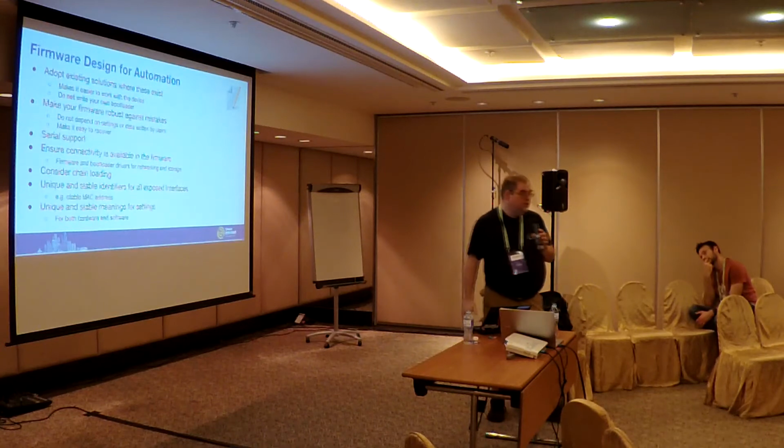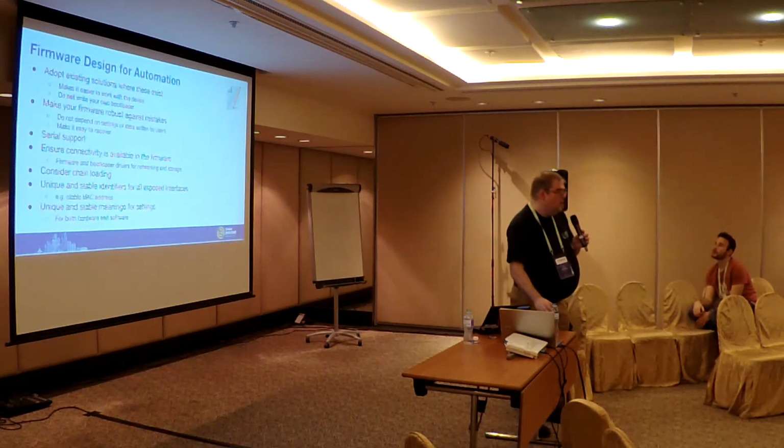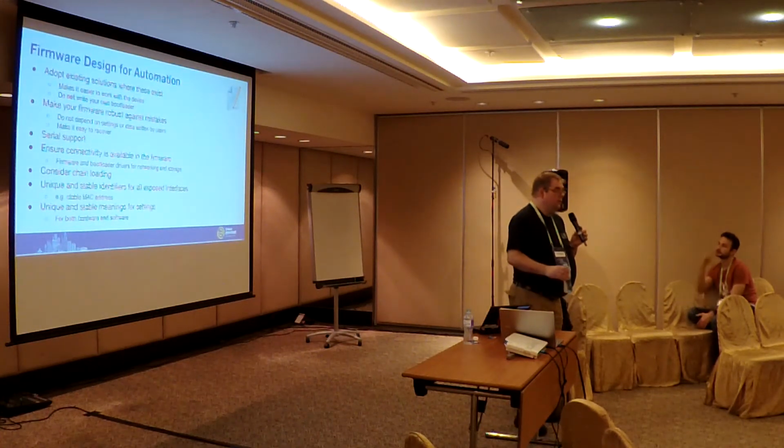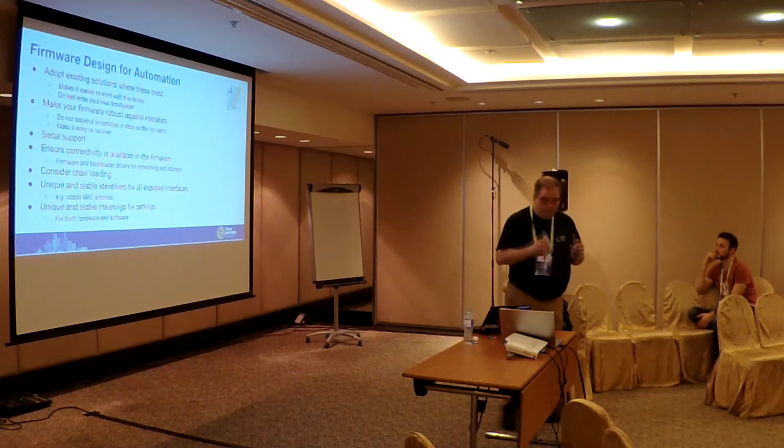Consider chain loading, as I mentioned earlier. Don't necessarily assume that your first level firmware has to be the thing we're talking to. We're okay talking 2 or 3 levels later on, so long as something is reliable. So by all means, your first level firmware can be really simple. If it then later comes up and we see U-Boot or GRUB, we're happy.